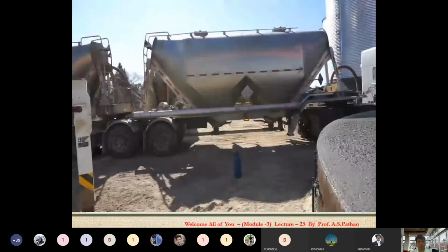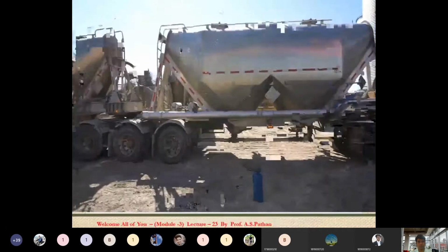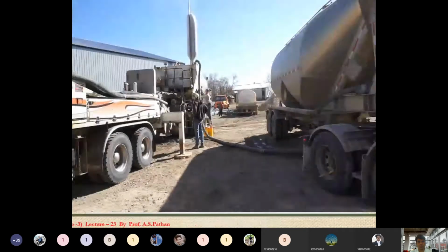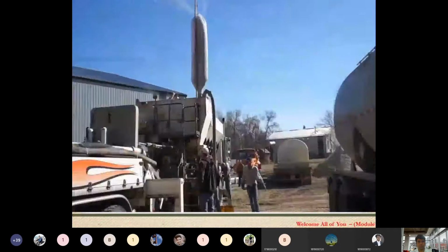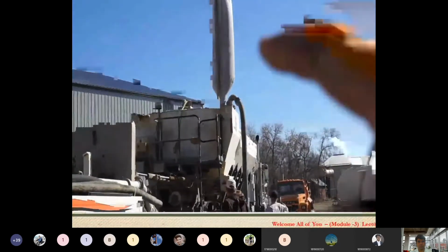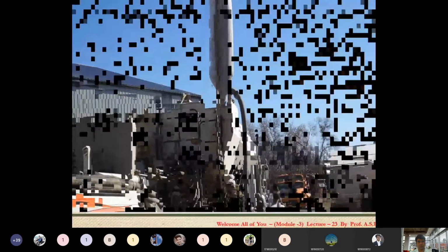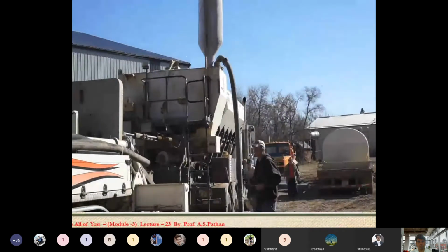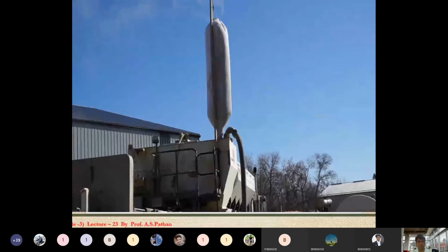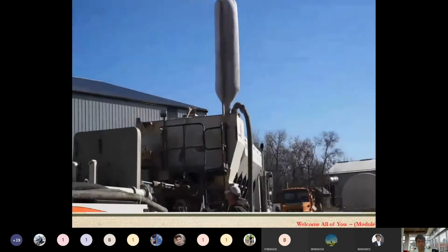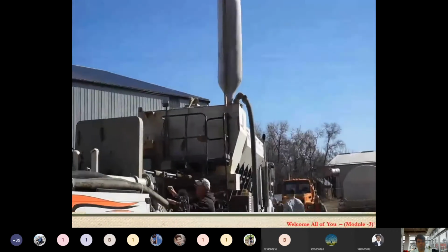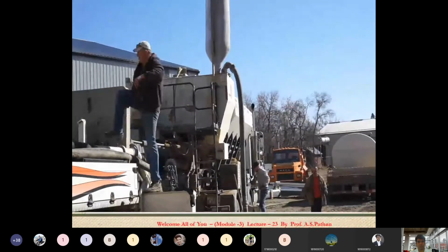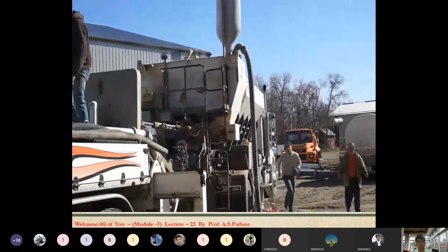And like I was saying, this is our cement bulker, which is hooked up directly to the truck there. And up top, on top of the truck, what you see right there is a dust bag that collects the dust, so that as you're blowing the cement powder into the bin, the dust doesn't all escape. Most of it stays in that bag as you fill the bin. And then we just fill the bin continuously, or start and stop as we need more powder.